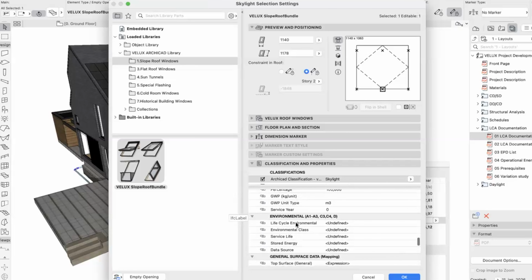So I might want to change that if I want to go for an even lower CO2 footprint. It could be steel screw foundations or point foundations or some other kind of foundation for the project. That's the whole calculation, and you can see the end result here on our project is 5.12 kilograms of CO2 per square meter per year.